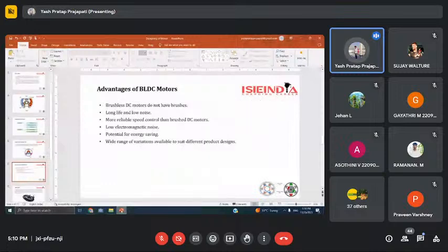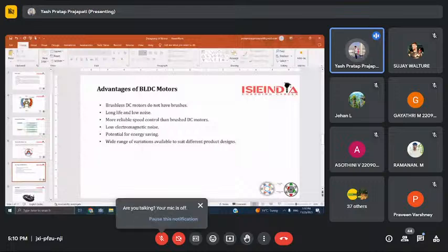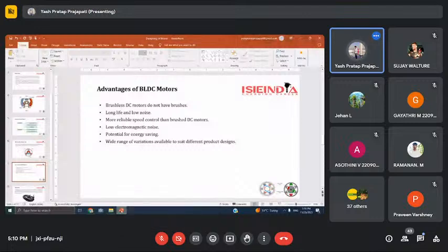What are the advantages of BLDC motors? A BLDC motor with three coils on the stator will have 6 electrical wires, two to each coil, extending from these. In most implementations, three of these wires will be connected internally, with the 3 remaining wires extending from the motor body.